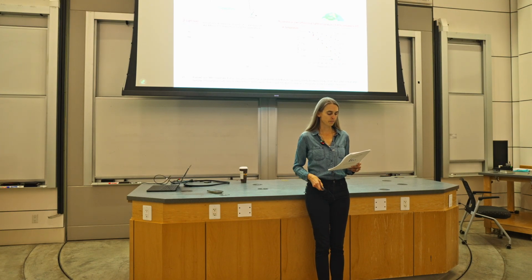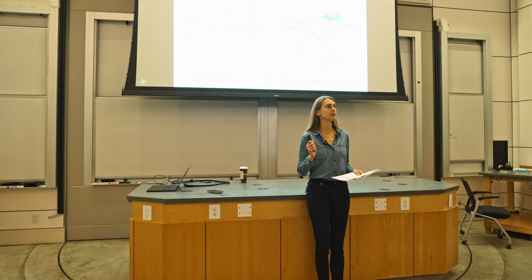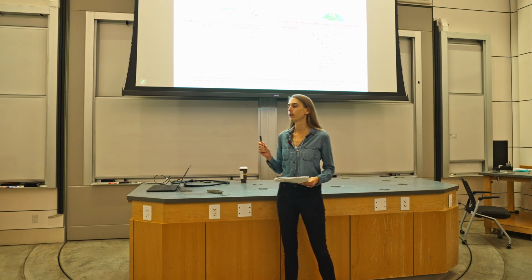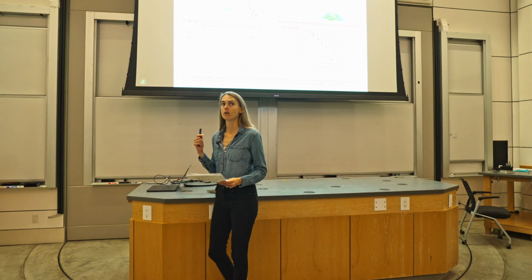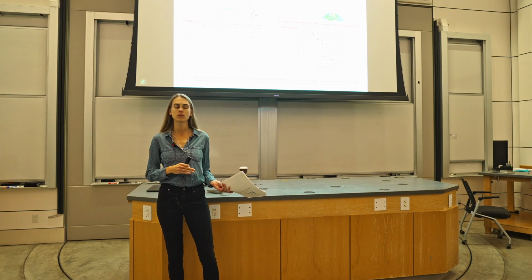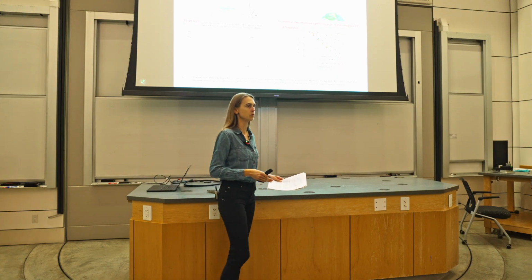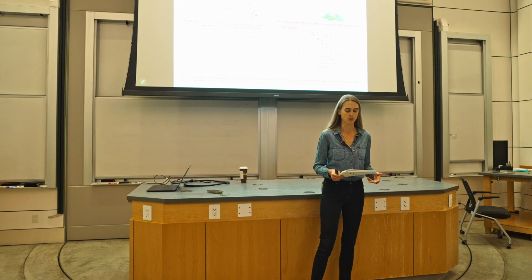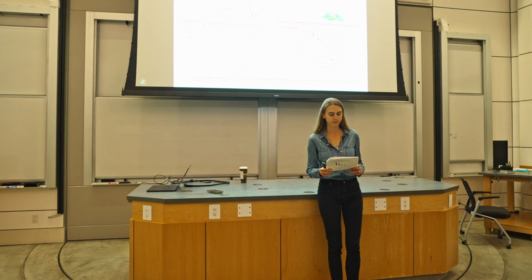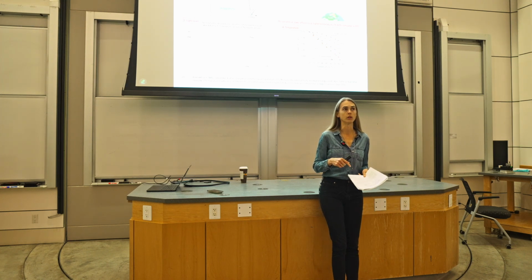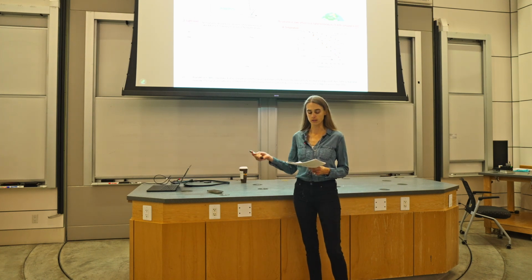But if you do see capacity rated in AC for solar panels, it accounts for inverter losses, and it also typically reflects not standard test conditions, but what are called performance test conditions, which are much more reflective of the conditions in which a solar panel is going to be operating under. So the AC rating for a solar PV panel is typically 20 to 25% lower than the DC rating, accounting for all these different factors.